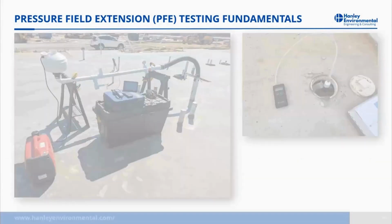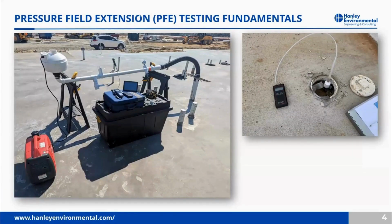Just a couple photos next showing the typical setup for pressure field extension testing. We've got a riser coming out of the slab, and that's connected to a manifold where we've got a vacuum gauge to measure the applied vacuum, a port to measure air speed within the manifold so we can calculate the airflow rate, a few valves to control the airflow and the applied vacuum, and then our fan to apply the vacuum. And finally, a test port on the right where we take the vacuum measurements at very low levels, down to 0.001 inches of water column.